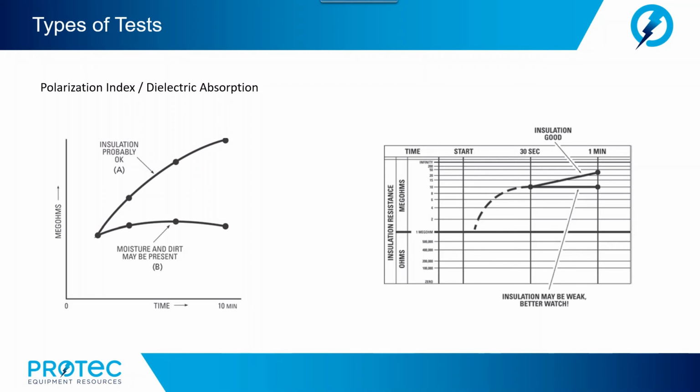Deteriorated insulation will pass relatively large amounts of leakage current at a constant rate for the applied voltage. This will flood out the charging effect, making the leakage current the more dominant of the currents flowing. Time resistance methods, as they are known, take advantage of this charging effect. Graphing the resistance reading at time intervals from initiation of the test yields a smooth rising curve for good insulation, but a flat graph for deteriorated or contaminated equipment.